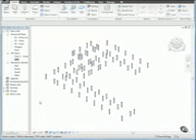As you create the model in Revit Structure, a simplified 3D representation of each element is created automatically. This simplified view is referred to as the analytical model. Each element is drawn with a different color to help identify specific analytical properties. For example, columns display as a blue line. You can export the analytical model to analysis and design applications.